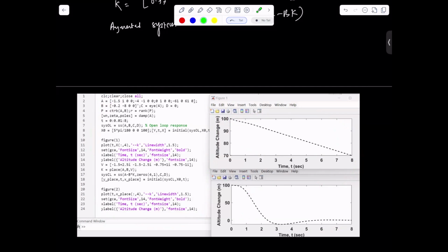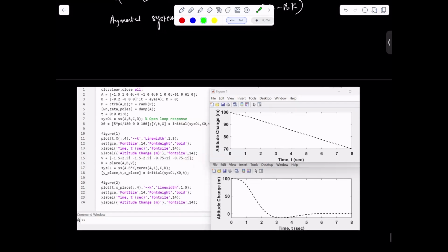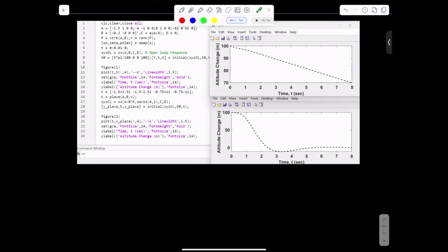So as of now, we have done many things on how to design control for an unstable system. Based on eigenvalues, you can define the system stability, and if the system is found to be unstable, you can design control. We came up with optimal control, state feedback control, and also how to develop the stability augmentation system for state space model systems. So we are almost at the end of the control synthesis in the linear domain.